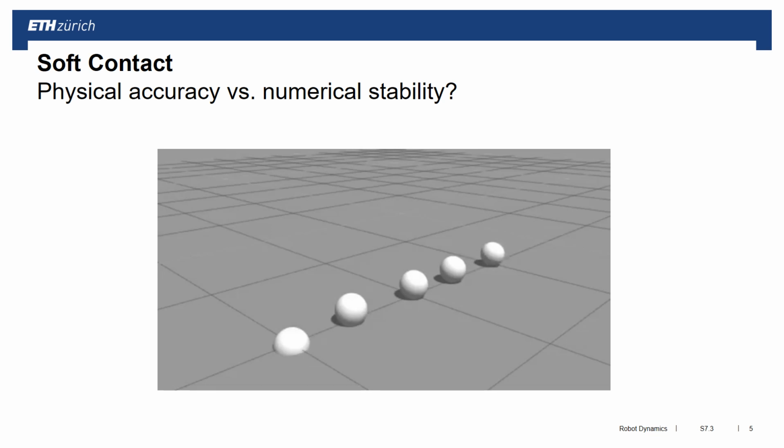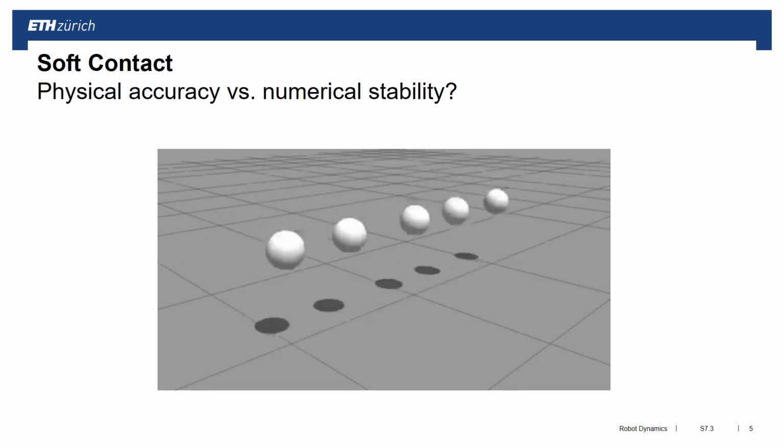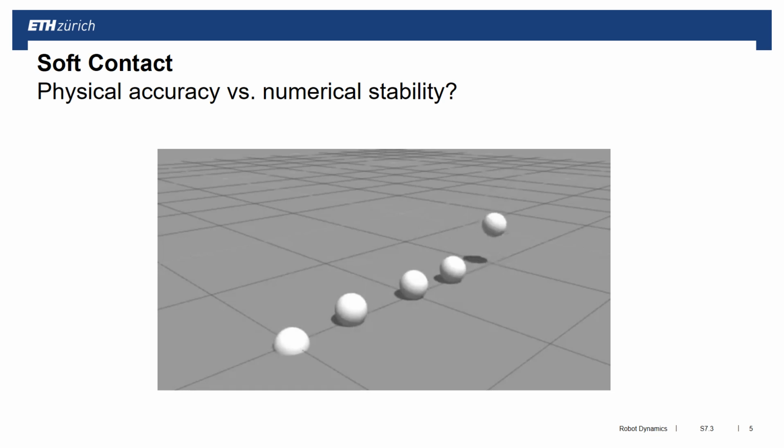And of course, the stiffer I make the system, the higher I make my damping, the more stiff my dynamics equations of motion become, the likelier it becomes unstable, the more problematic numerical errors become, the slower my simulation will be. So that will always result in a trade-off between tuning these contact parameters to be some sort of physical representation, but much more to become essentially a numerical tuning parameter to get a nice interaction behavior.